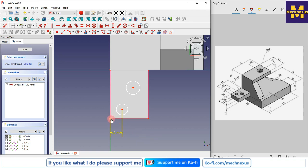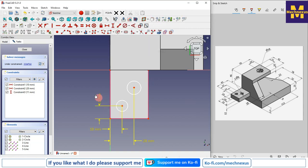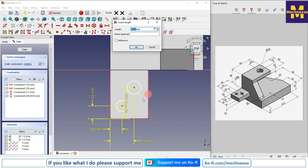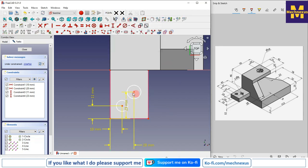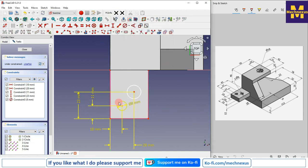and this to this is 20, this point to this point is 11 mm, and this point to this point is 23, and this hole diameter is 8 mm, and make this and this equal.